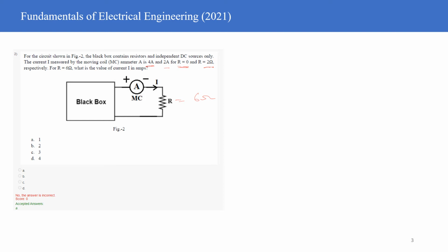So let me ask you, Sharad, what's the value of the resistance of this ammeter? Is there some resistance in the ammeter, or is the resistance equal to zero? Normally, the minimum resistance should be there. Correct. So we will assume here the ideal situation. So in the ideal situation, the ammeter is a zero resistance device, right? So the only resistance present in the circuit is this resistance R, which is unknown to us, and it's changing, right? So how to go forward here, Sharad?